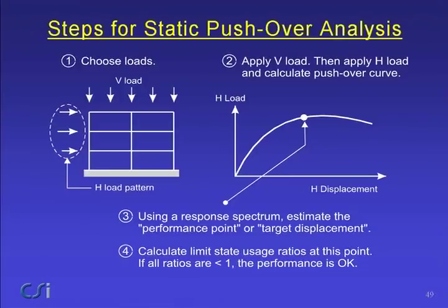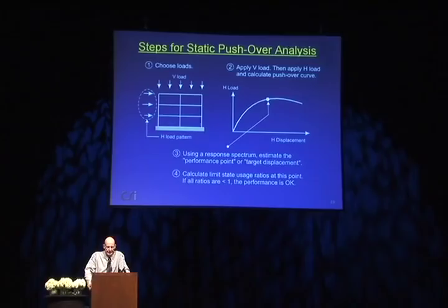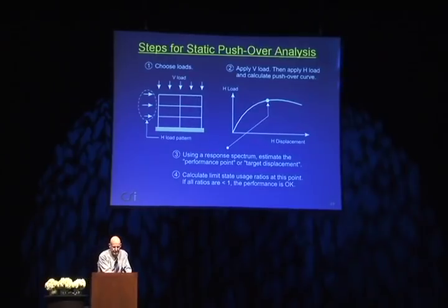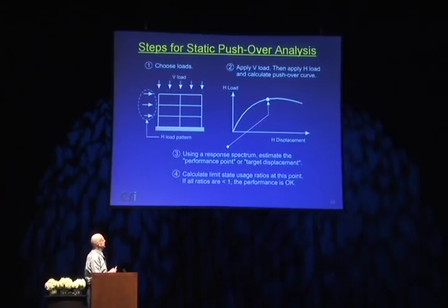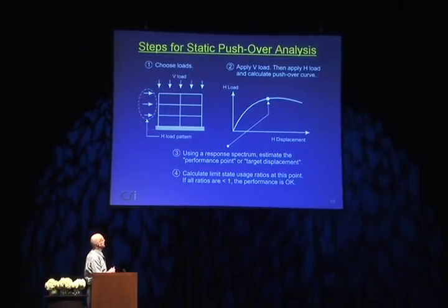possibly time-consuming analysis. Static pushover analysis has been around as a way to reduce the amount of computation, basically. And this slide indicates the steps in pushover analysis. And firstly, you choose the load. You specify the gravity load vertically and some horizontal load pattern.